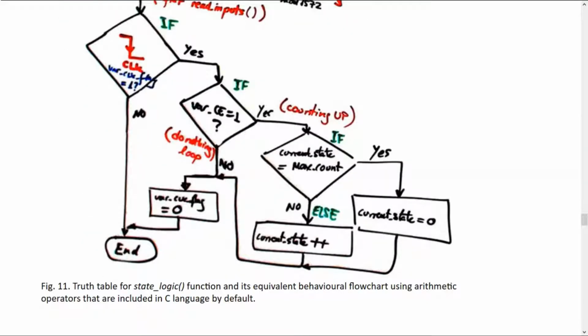But this time you see there is no case. You cannot have a case or a switch case of 1572 levels. That is impossible. Okay, what is possible now and a lot simpler is doing that kind of thing. A general if associated to the clock detection. Is it right that you have this flag set high? Yes, if this happens now you may do something or not, depending on the bar count enable. If this count enable is set low, the level, you see, you go back without doing anything. So that's simple.